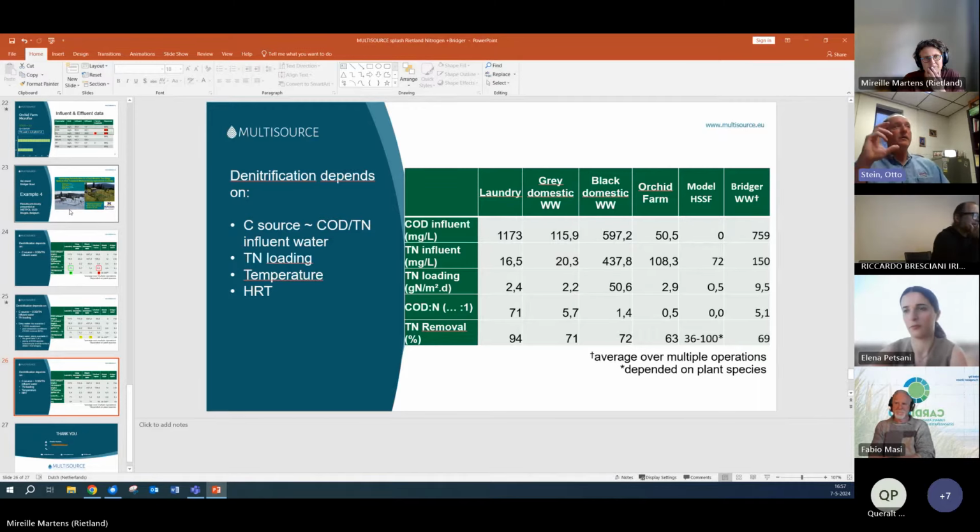If your dose volume was exactly equal to your specific retention and there was no mixing in the system, that would be the optimal dose volume. If you put in more than the specific retention of the system, anything bigger than a value of 1 is going to go right through. But there's also a lot of mixing that goes on, so 1 is a theoretical best, but it's always going to have to be lower than that.